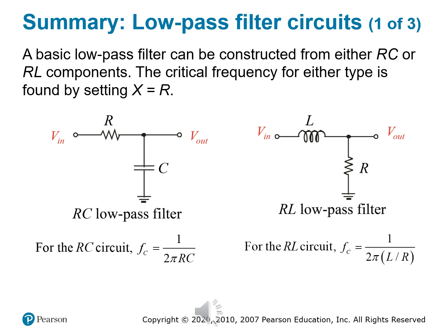The RC low-pass filter. So go ahead and imagine this. You've got a resistor in series with a capacitor that heads straight to ground, and your input voltage, V sub in, hits the resistor, and you measure your output V sub out across the capacitor. As frequency increases, the capacitor starts acting like a short and pulls the signal away from the output. So it starts getting attenuated, in other words. And that's how it filters out high frequencies. The critical frequency, or the cutoff frequency, we can calculate with the formula f sub c is equal to 1 over 2 times pi times R times C.